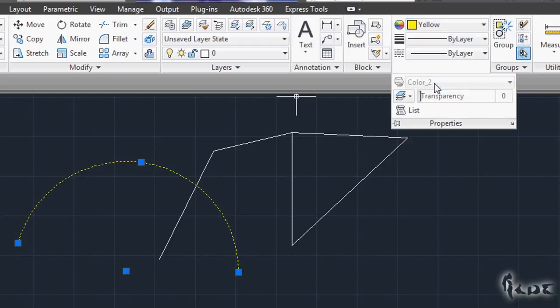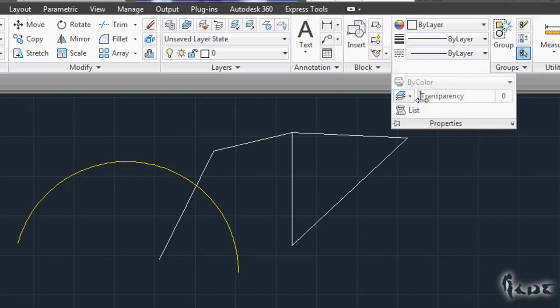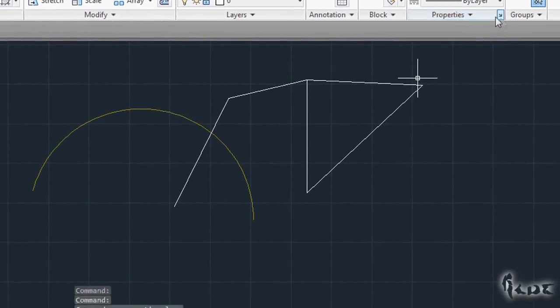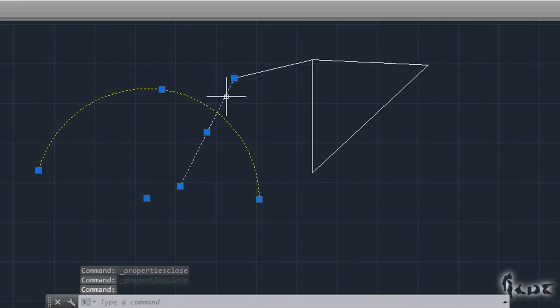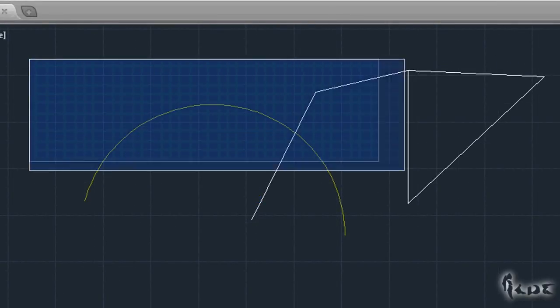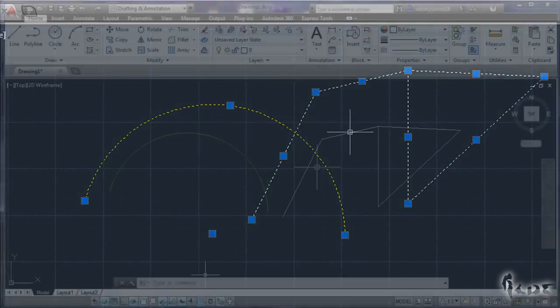For example, select an object and go to Properties section. Here you can choose color, thickness, kind of line and transparency. Just click at the bottom. These are just related to the object currently selected. You will need to select more objects to apply the same properties all at once. To do this, you can select objects one by one by clicking on them singularly, or you can simply click and drag your mouse across all the objects you need to select in one single shot.